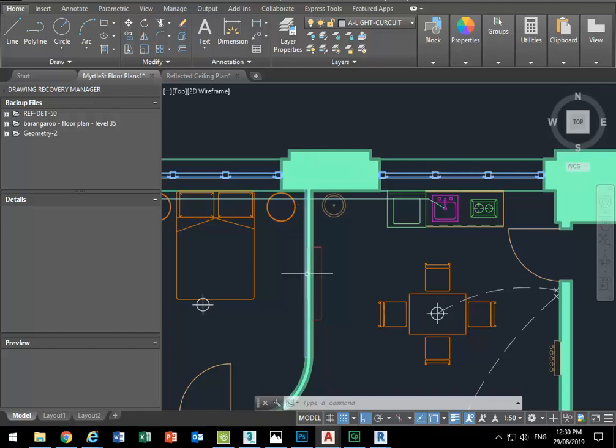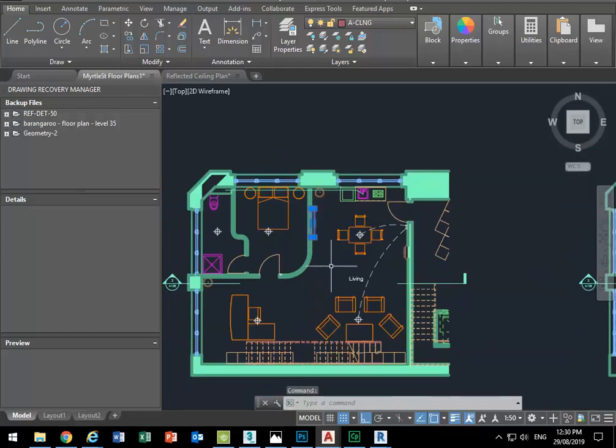Oh, right. Okay, well, maybe it might be better for some of your designs, rather than doing a split system, to have a ducted system, and then have a central air conditioning system. I don't want to get too far into that, because technically you need air handling units on each level as well, which you wouldn't have planned for. Yeah. But I won't be too long. I'll finish in a minute. So maybe we'll say you can put ducting in, and we'll just say that, because you're not going to show the whole level, you have a space for your air handling units somewhere.